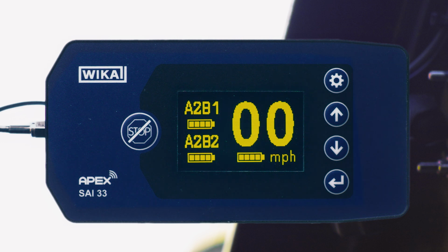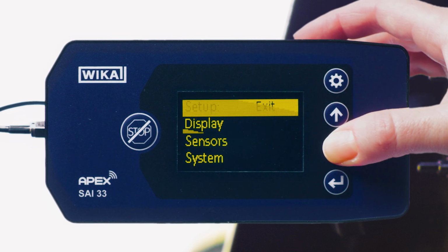The system also features digital outputs. Digital output 1 is always set to all connected anti-2-block sensors and cannot be reconfigured. Digital output 2 can be configured to activate when either an anti-2-block switch is triggered or a wind speed limit is reached. To configure digital output 2, select it from the menu.